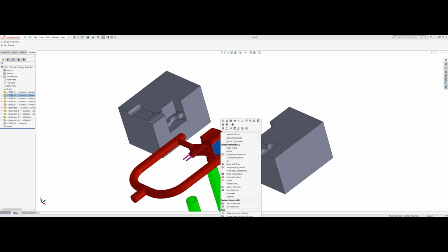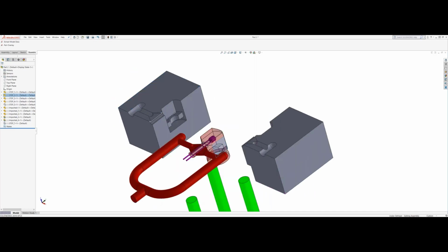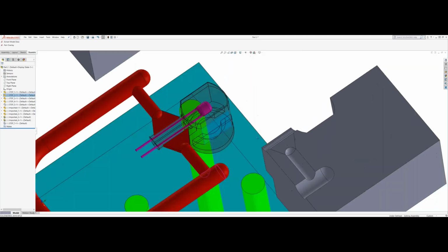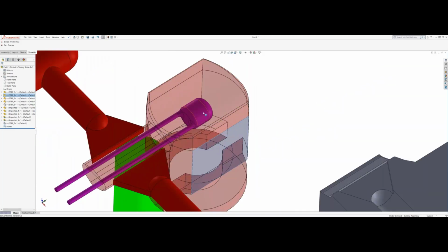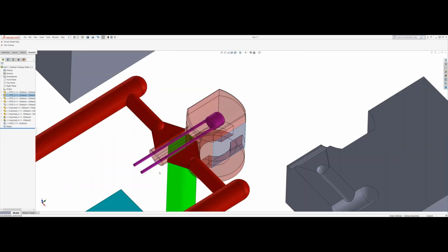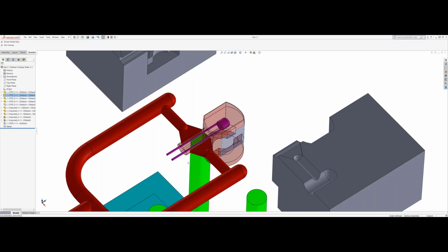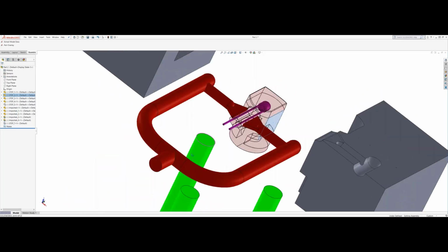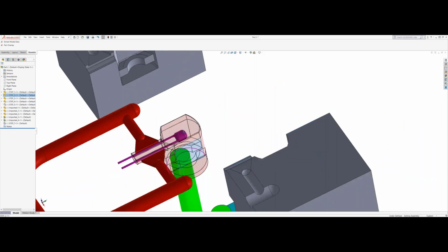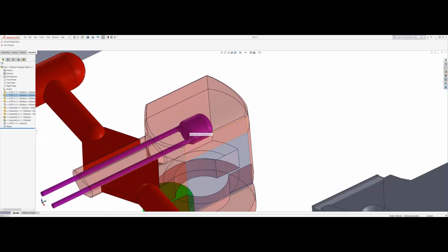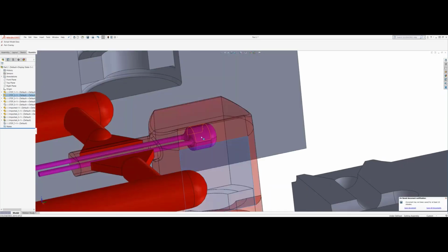So we can see what we're overmolding here, this thermistor. We didn't have much room or much to hold on to. We really had these two wires that are leading into the part. So we had to get creative with the gating, and there weren't any special requirements as far as where this portion of the thermistor ended up.